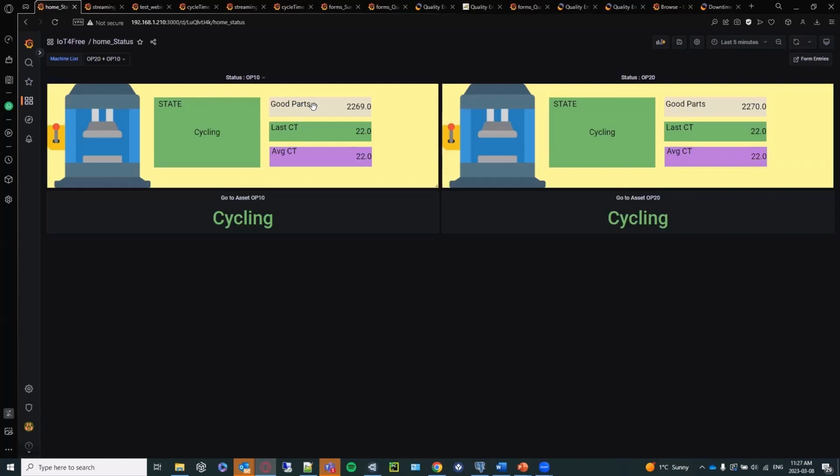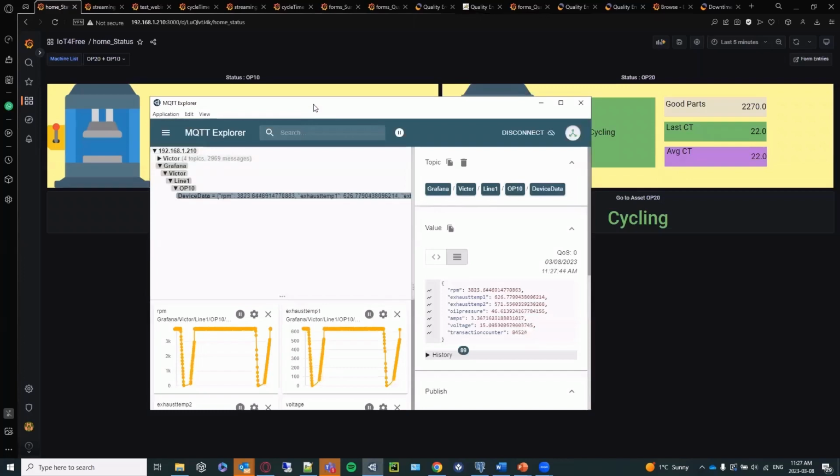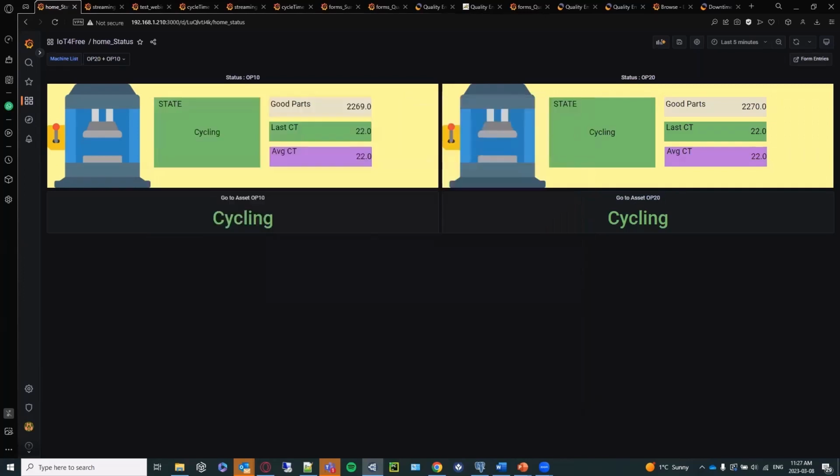Yeah. So, this really is a viable solution for a company that only has a limited number of equipment, that you're going to be able to take that information, connect to those PLCs, connect to sensors that you add to the devices and so forth, gather that information through either just an MQTT type solution, or you may need to get something like a Kepware license for certain types of equipment that doesn't have some of that connectivity that exists. But you're not looking at downstream ongoing license payments for that, right?